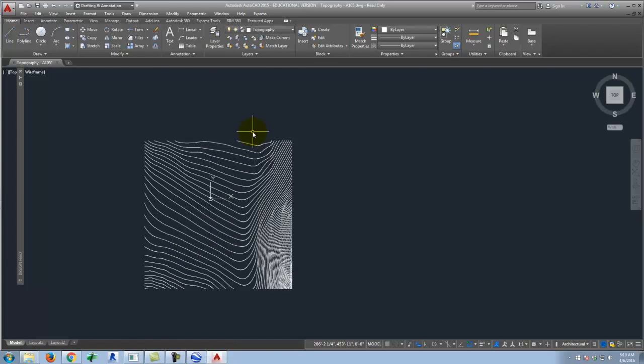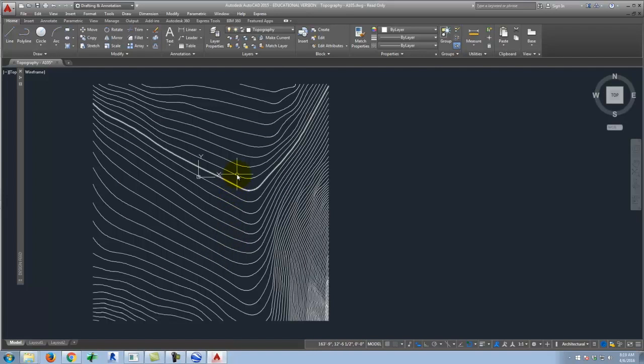So it's going down this direction. So this is your building site. You can build anywhere on this site that you want. The contour intervals are 1 foot apart. So as you step up from here, each one of these that you pass is 1 foot. So it's relatively flat, but there's a little bit of slope on the site. Does that make sense?